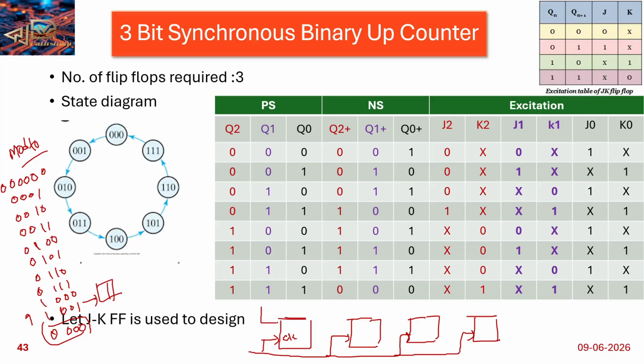Here I am giving the data input D1 with output Q1, D2 with output Q2, D3 with output Q3, and D4 with output Q4. For the final condition, Q1 and Q4 are 1 here, and they are connected to a NAND gate.